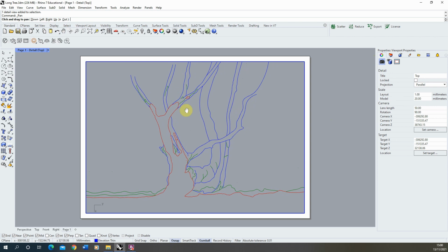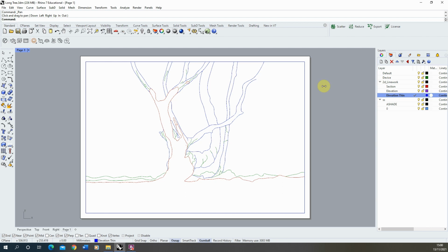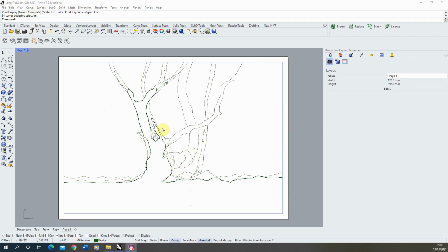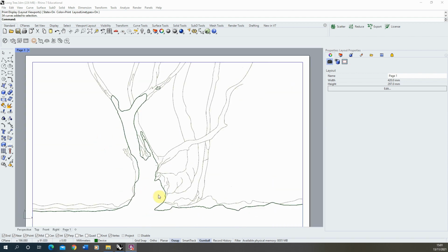And because we've set particular line weights on that already in my layers, and I've got print width set to this, I can type in print display, turn it on, there. See, now those line weights are turned on, we've got a nice fixed section line there and thinner lines for surroundings, and we can start to draw in more detail to that as well. But you can see, because we're using this 3D scan, we're getting this level of detail that you wouldn't normally be able to get from just drawing or trying to estimate this. It's actually an accurate level of detail for this model, and we've got a nice groundscape as well. So it starts to build in a lot of complexity and detail into your drawings using this method.